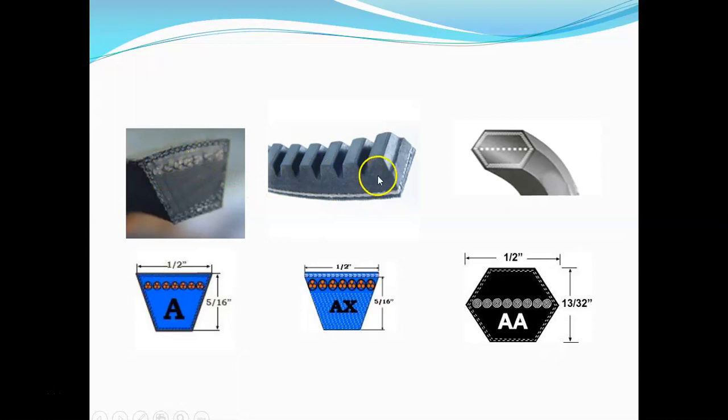So here's a picture of a cogged belt. I should put this picture on the slide itself. That way you can get a visual while we're talking about it. So the cogged belt is just notches cut inside. So they can actually make a tighter loop through a smaller sheave. And then since there's more surface area showing open to the air, it keeps the belt cooler. Again, there's really no less strength involved in these because your strength is coming from this core in the top.